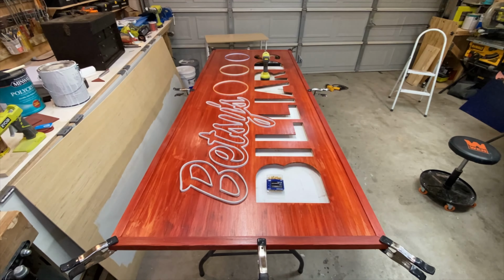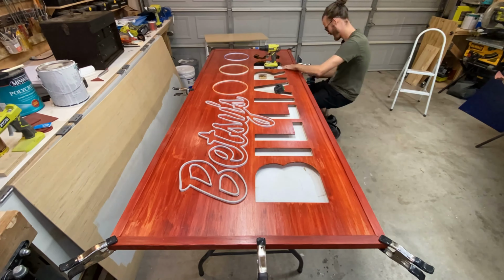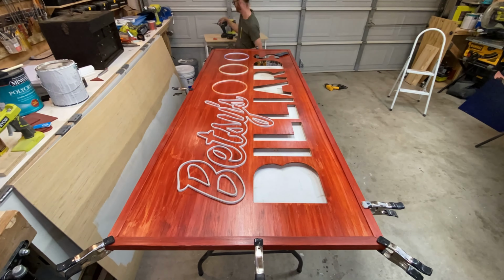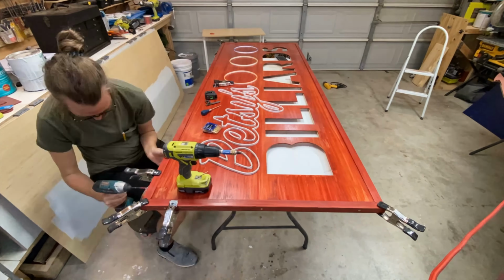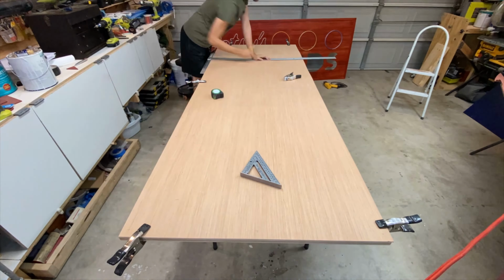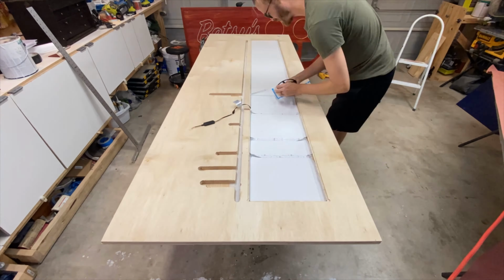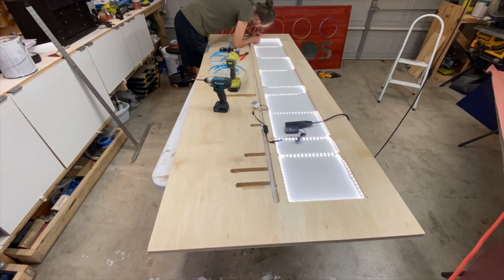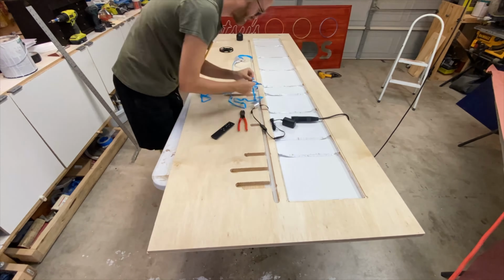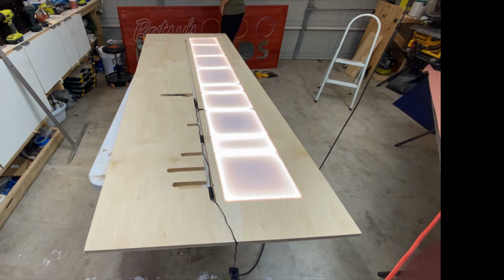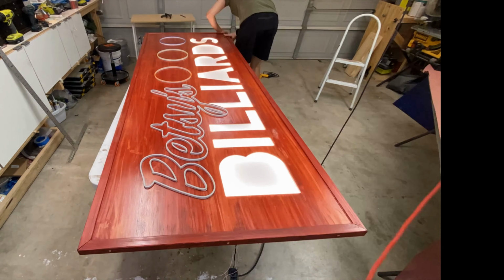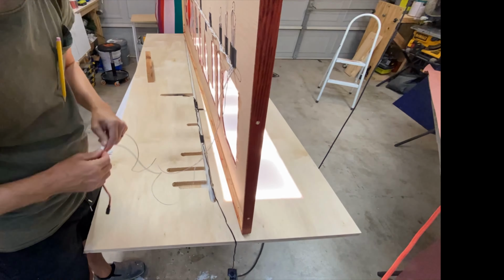Here you can see how I'm attaching the frame of the sign to the side of the sign. I'm pre-drilling holes with a countersink bit and screwing them in using some brass screws. I then attached the back to the middle using the same 3/4-inch brass screws. Finally, it was time to install and wire up the LEDs that will go behind the acrylic sheets. I had to solder together 2 long strips to make it work. Next, it was time to set in the acrylic in the front of the sign to get a first look on how our sign will look.